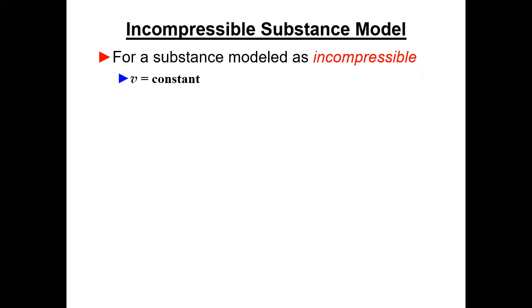Specific volume is constant, and that's 1 over density. So you know your density, pounds mass per cubic foot, and that's going to stay the same. You can press however hard you want to, but you can't move the molecules closer together or further apart. So that makes internal energy only a function of temperature.